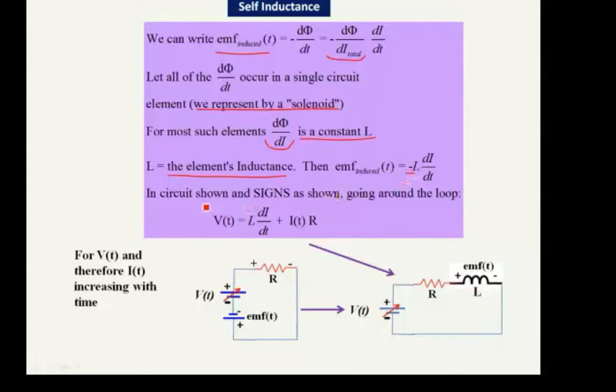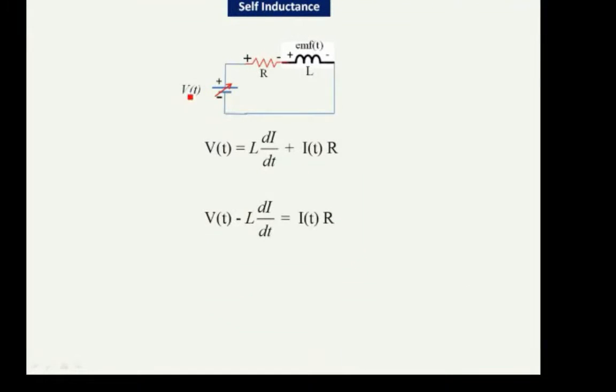So if you look at the circuit that we've had here, we've replaced the EMF as a function of time with L times di/dt. In order to get the EMF, it's going to be L times di/dt. Okay, so right up here, the EMF induced is equal to L di/dt with the correct sign. Rewriting the potential, we have the potential that we're driving all of this with. Here's the potential that's dropped across the inductor, and here's the potential dropped across the resistor. So if we look again, here's our voltage source, the real one. We've got this L di/dt plus I times R.